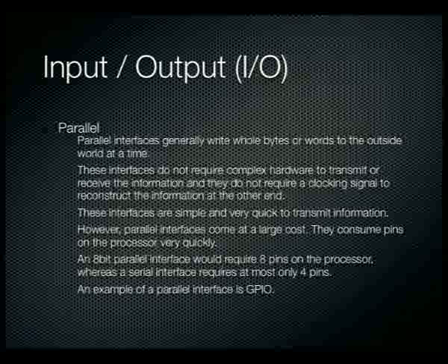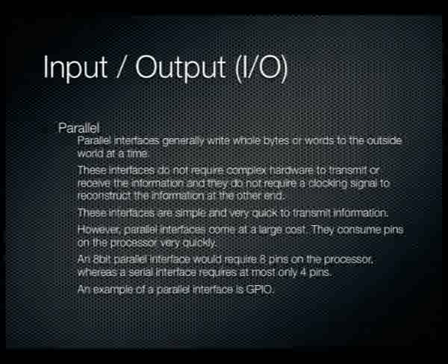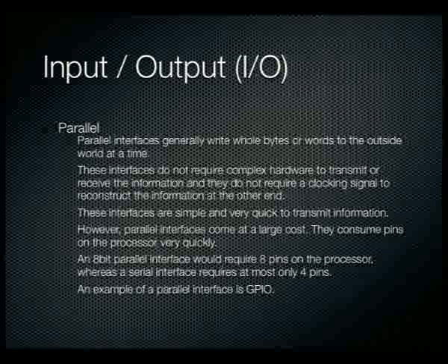And if you've only got an 8-pin processor like one of those 8-pin PICs, then of course you don't even have that number of GPIO lines anyway. You've only got a top of 6 general purpose I/O lines, and if you use all 6 of them, then of course you've used up all the input-output components of your processor. So parallel GPIO is very costly as far as pin counts are concerned.